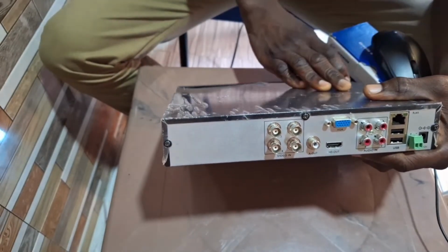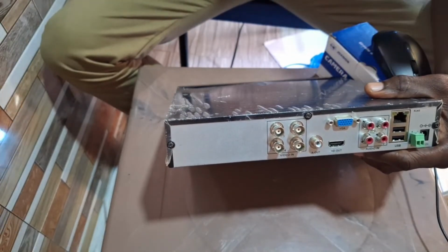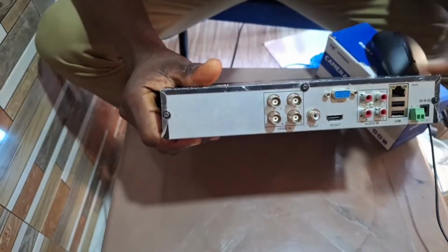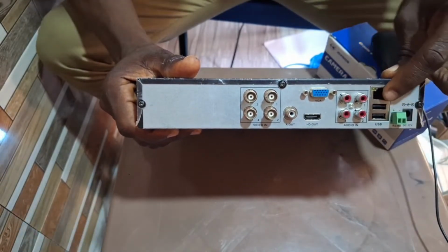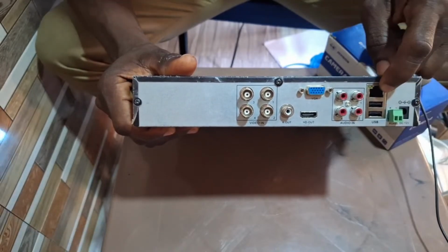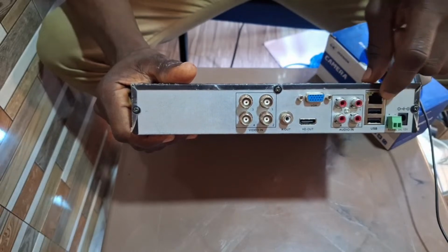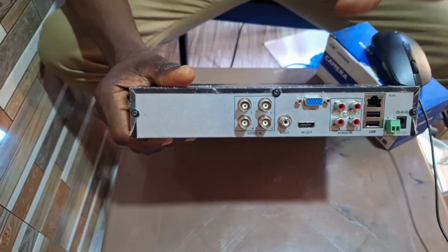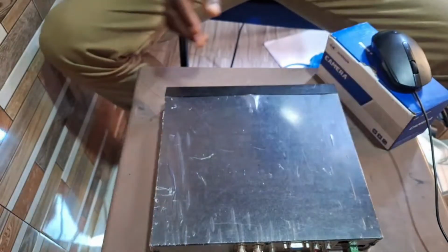And I was mentioning in my introduction that the DVR, which is the recorder for analog CCTV systems, is able to give you the ability to view analog cameras online. That is possible through the Ethernet port that is here. Through this port, in subsequent lessons, we're going to learn how to put the DVR online. So through a network cable plugged in here, you can connect internet into the DVR so that you can view the cameras on the internet.